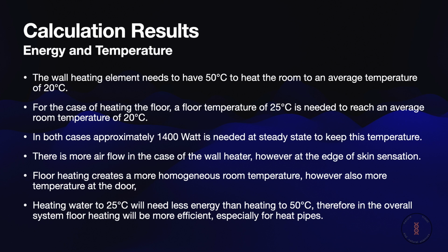Efficiency advantage. The primary benefit of underfloor heating is the significantly lower operating temperature, 25 degrees Celsius versus 50 degrees Celsius. This allows for a much higher system efficiency, particularly when integrated with modern heat pump technology, as the required temperature lift is minimized.